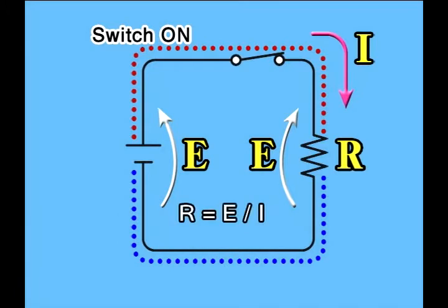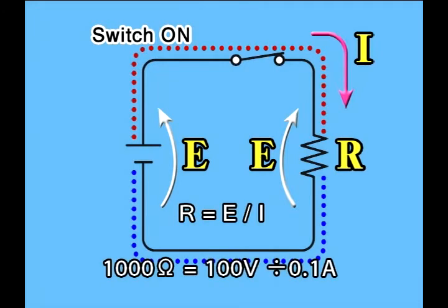We can also deduce that voltage of 100 volts is generated between the resistor terminals when a current of 1 amp is passed through a resistor of 100 ohms. For example, resistance of 100 ohms will be used to convert current of 0.1 amps into 100 volts.